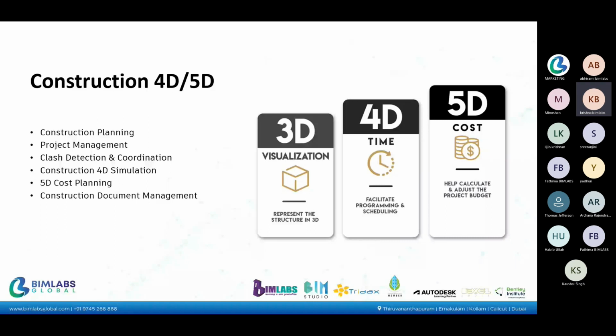In construction, we use software like Primavera for this planning stage. If we have that planning data, the schedule data, you can directly enter it in the Navisworks software. For example, you can add footing from the 5th to 8th day, give the number of days, then columns, then slab. Likewise you can do the activities and make a video. You can do the 4D simulation.